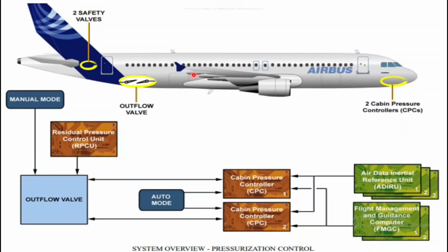Whatever compartment is pressurized, its door is made mostly of aluminum alloy, like the passenger door, cargo door, bulk cargo door, and avionics ventilation door. Whatever area is unpressurized, that door is made of carbon fiber material, for example composite material. So the unpressurized areas are all made of composite material, like the pack belly fairings. The APU compartment is also composite.